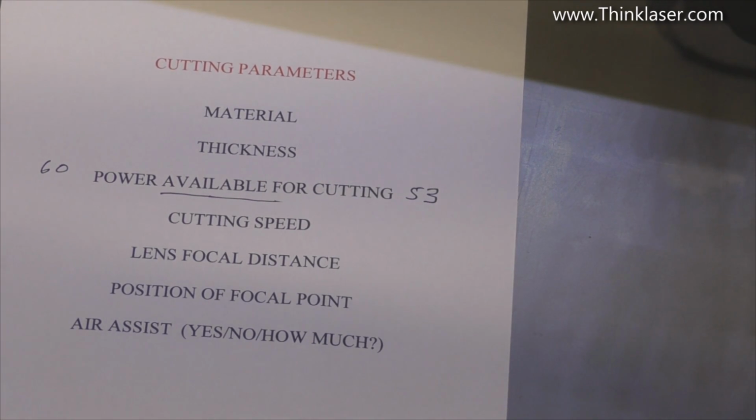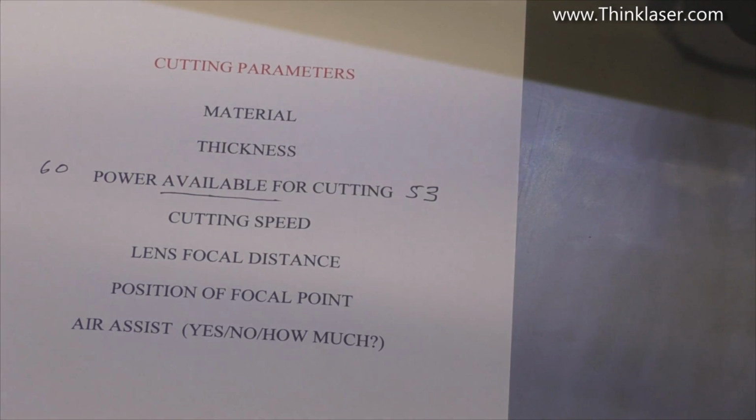I suppose theoretically any supplier of cutting parameters cannot legislate for the quality of your machine, and so consequently they give you best condition. But we don't know the condition of their machine when they set it up. Maybe their machine was similar, maybe it wasn't. We just don't know. So the whole thing about cutting parameters is uncertainty.